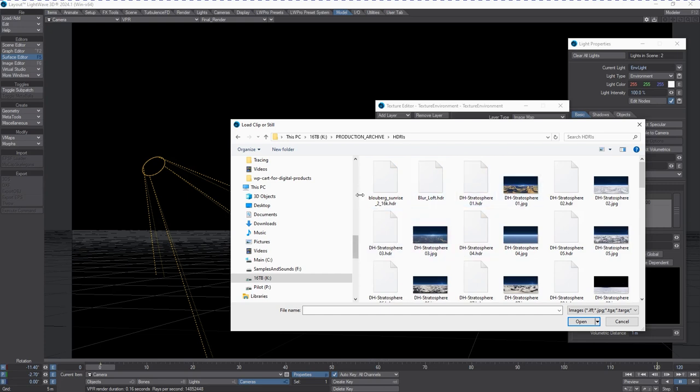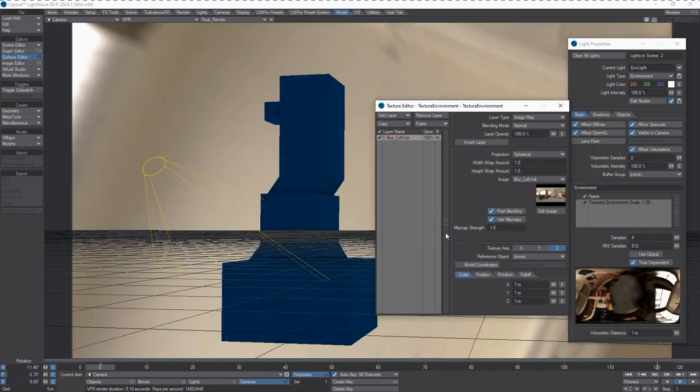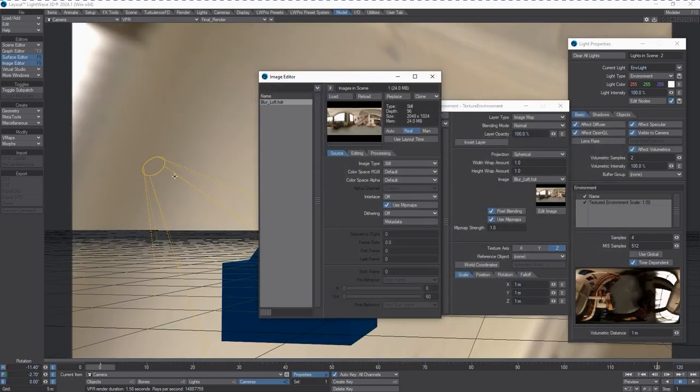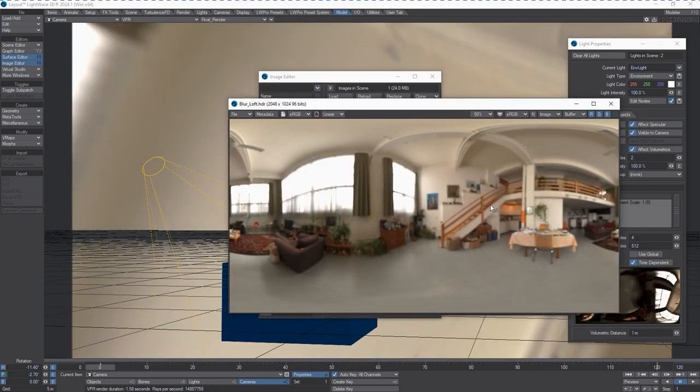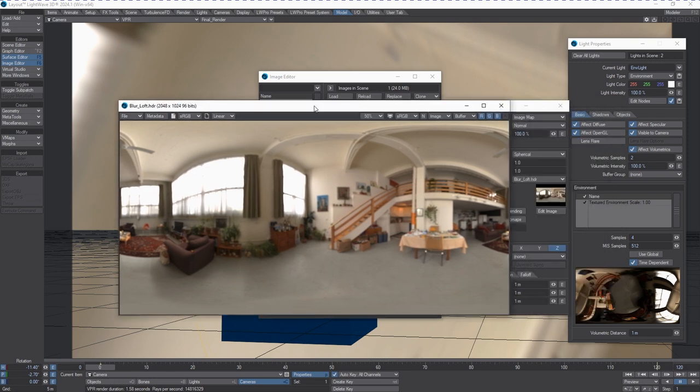So for this, what I'm going to do is I'm going to go and grab a very standard issue HDRI called Blur Loft. We've seen this all over the place. Let's take a look at it. And here we have an HDRI, and this is several stops, if you are familiar with photography, of information into a high dynamic range image. So it has basically 96 bits of color information per pixel, so RGB. Each one of those has 96 bits of image depth.